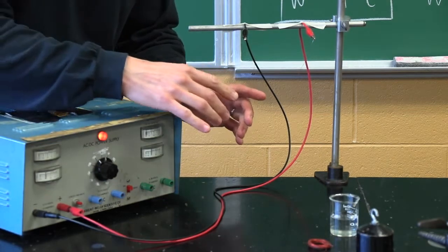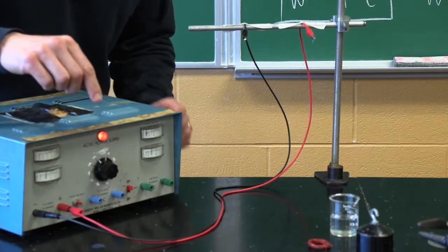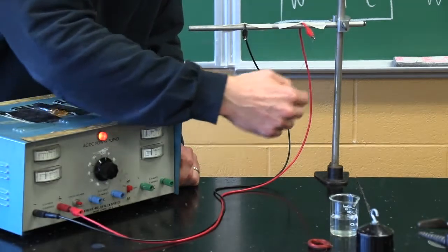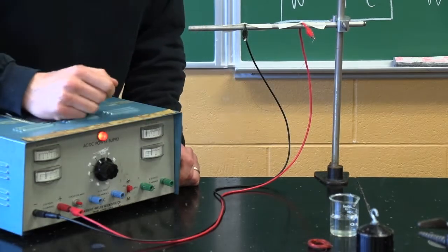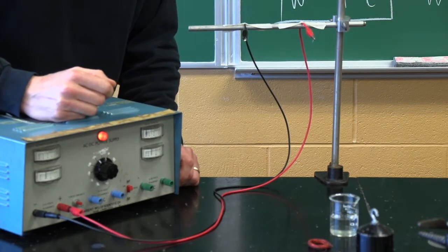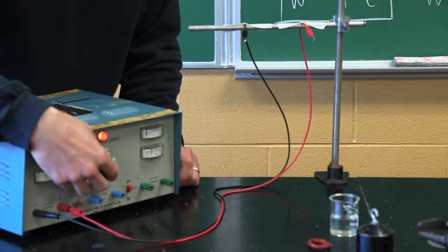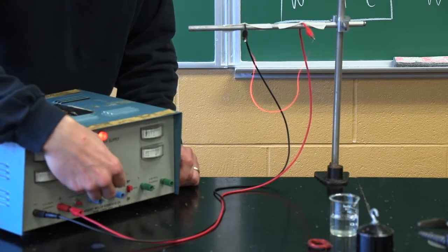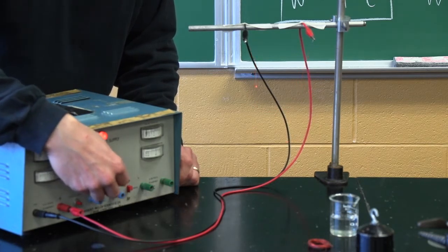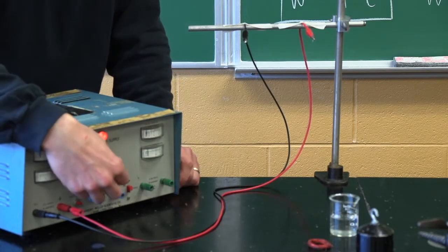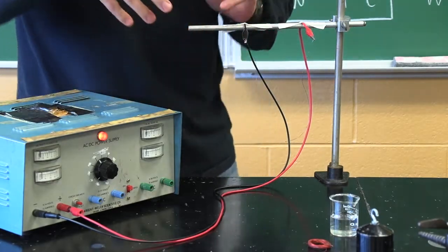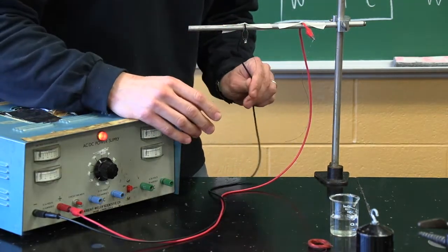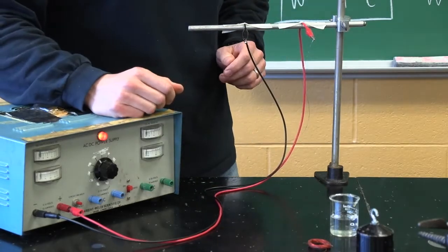But so we're at this equilibrium, but if I crank this voltage higher, it'll pass more current through that wire, so the electrons going through the wire will slam into the atoms even more rapidly, producing more heat so fast that the wire will not be able to dissipate it fast enough. And then we're going to see something pretty dramatic happen. The wire actually melted. I melted metal with the electric current passing through. So that is a demonstration of power going in extremely rapidly, heating up the copper wires.